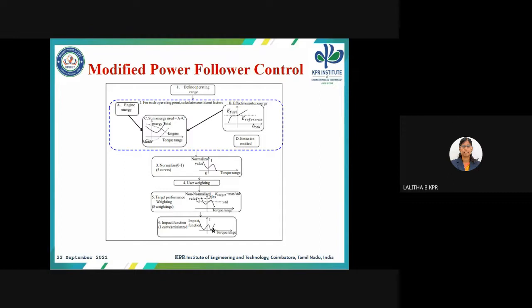The output of the IC engine for cold and hot operation is: the cold consumption output is the hot consumption times K1 plus (95 minus IC engine temperature) divided by 75, times K2. Likewise, we can have the hot consumption output equation. The second step in calculating the constituent factors is to calculate the effective fuel energy that would be consumed by the electric motor for a time interval.